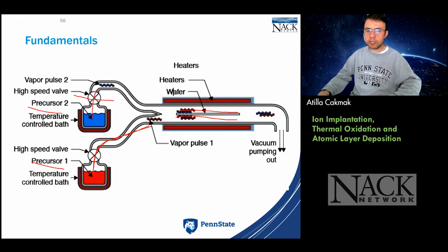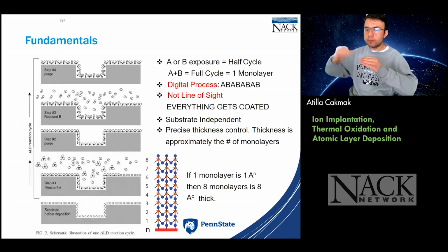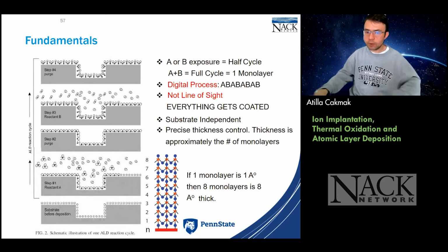I'll talk about it more so that we're going to be more clear. So we have a balance between the chemistry and desorption, saturation, adsorption and desorption. The precursor can come down and can be desorbed to the outside or can go into the reaction here. By the way, ALD is generally a much lower temperature deposition technique, so it's an advantage compared to CVD. But it's a growth that's happening layer by layer, atomic layer. That's why it's given this name, one atom at a time. So that's the rate that we go with.